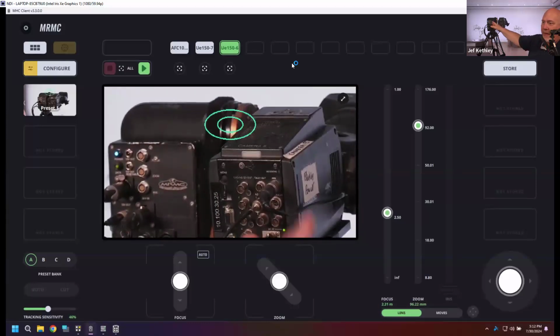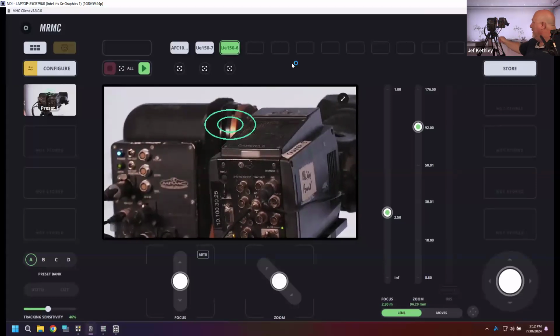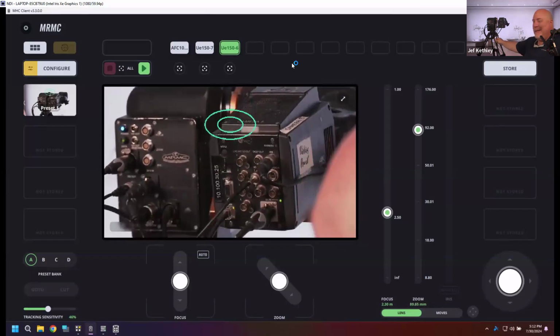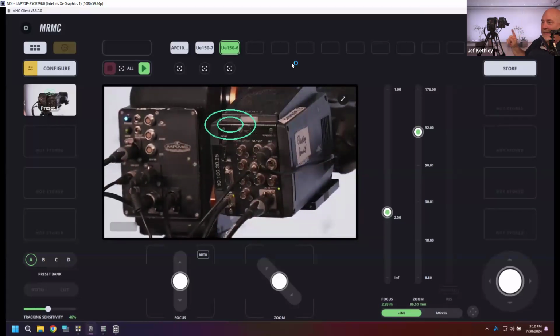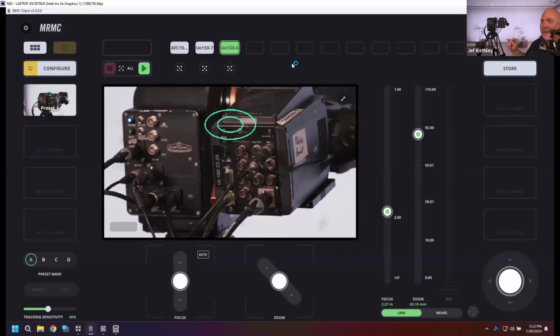So we power the head, and the head powers off a 24-volt DC. That's this cable right here. And it's kind of weird in that it's a 3-pin cable, and I really didn't like that at first, because it was like, okay, somebody from audio is going to really screw up my world, either by putting 48 volts into this, or we're going to get some audio into our camera feed for power. But it hasn't happened. We've just been really careful about it.